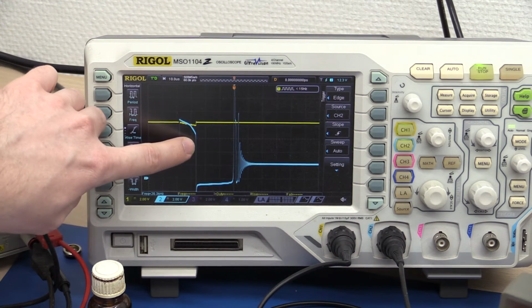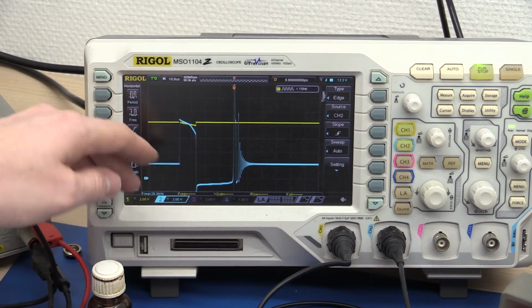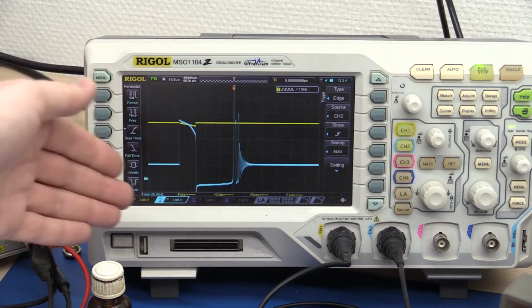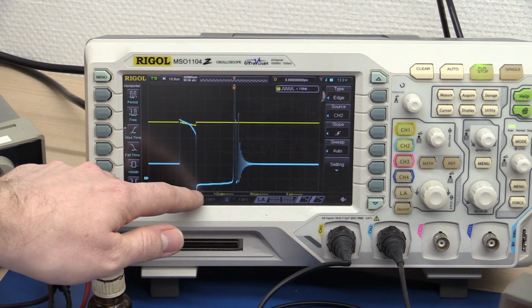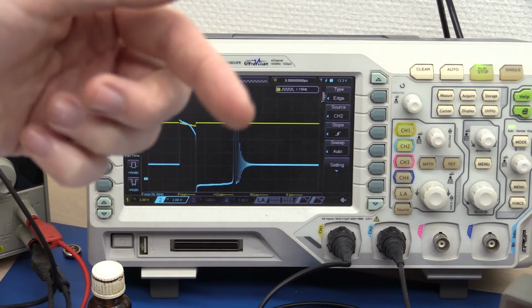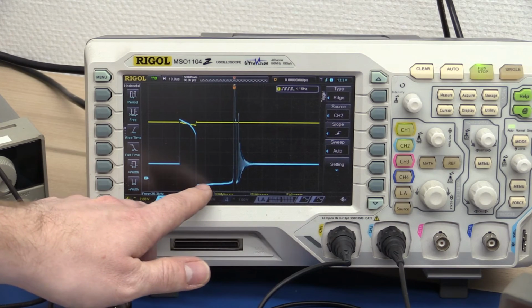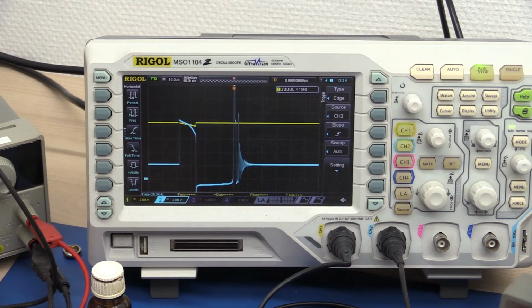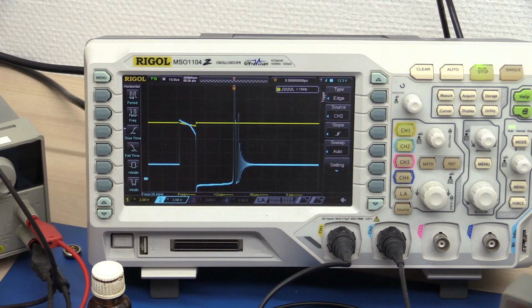When the transistor switches off, you can see the voltage drops all the way below zero here, and that's because the inductor wants to keep pushing current. Now we got it started, it doesn't want to stop again, but the diode catches that, and it's able to complete the loop through the ground so that the inductor can get rid of its energy. As long as the line is low here, that's when the diode is conducting, and once it stops we have some ringing, probably due to some stray capacitance, and perhaps my long ground leads on the probe doesn't help either.